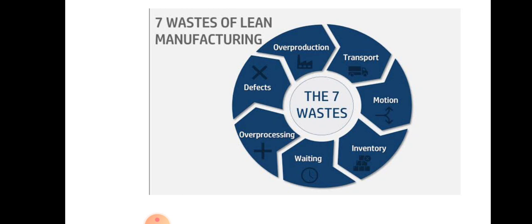So here, referring to core lean manufacturing methodology, process mapping should include facility layout and optimized workplace design that includes analysis of the distance of motion within the space, as well as the location of parts, supplies, and tools within the space, right? So an effective process map is developed. Proper utilization of the space should be captured, and it should be well designed and documented based on the standard work. Some of the common motion waste examples include poor workstation layout, poor production planning, poor process design, shared equipment and machines, and lack of production standards.